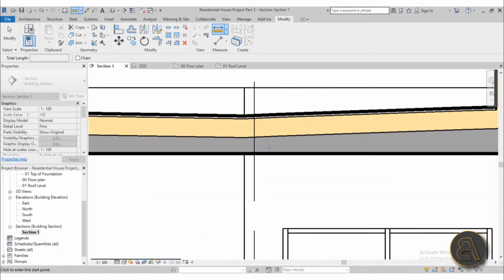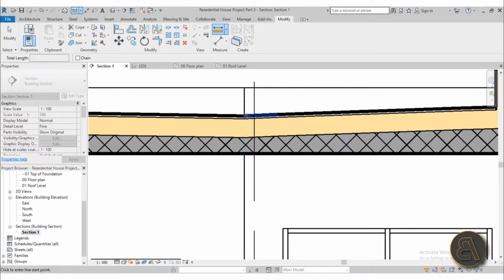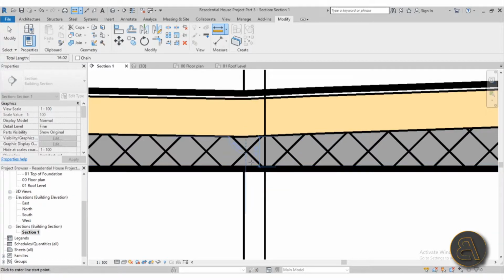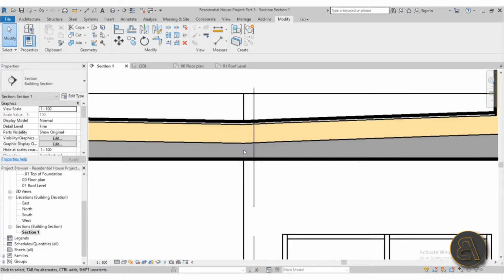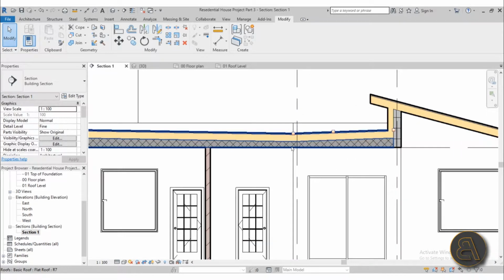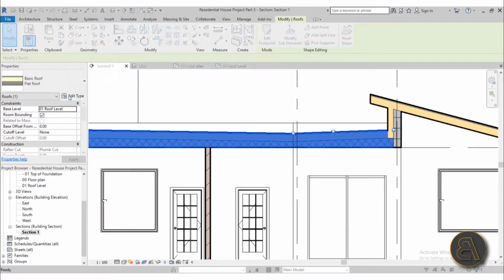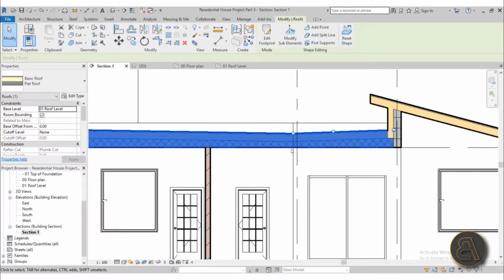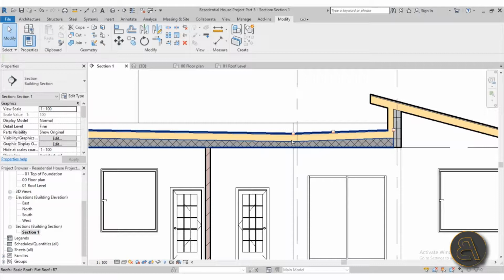And now if I go here and measure, and let's go to the center point that's over here, and if I just measure the height of this layer, you're going to notice that it's 16 centimeters, which is the actual height that we set up. So by adding height at the edges, our concrete slab keeps the minimum thickness of 16 as we set up in our structure. So it kept that 16 here in the thinnest part, and that's why we increased it on the edges.